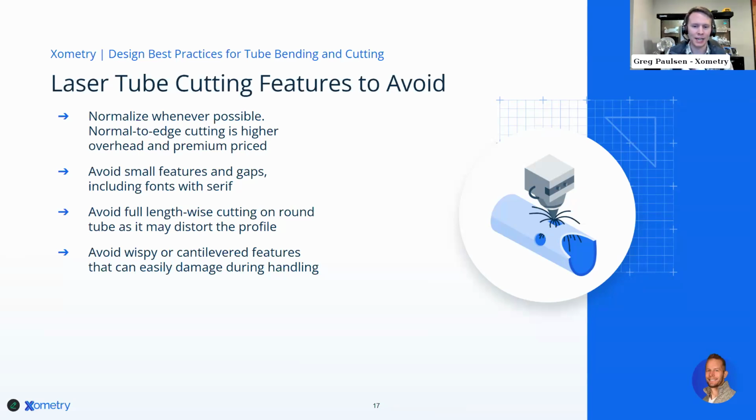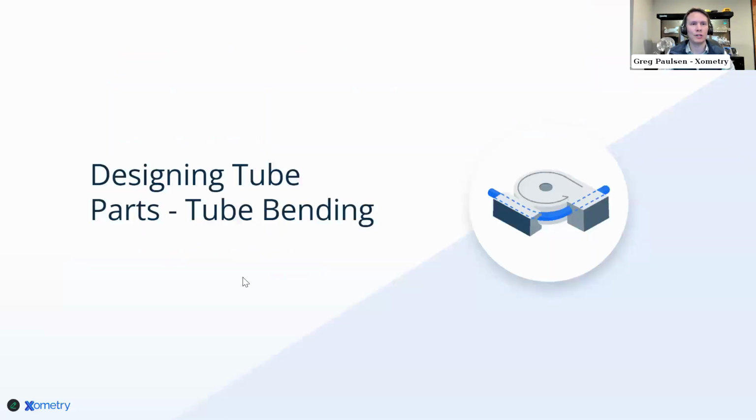But then my next approach is to make 2 or 3 of them and see if it holds the shape that I'm intending before we go and cut hundreds of them. Right, so it's not saying we can't do it, but it's something to be mindful of, especially in your design, because this has a full through cut, and there's a good chance that it may either want to close or flare out on me once I apply that heat and stress to those parts.